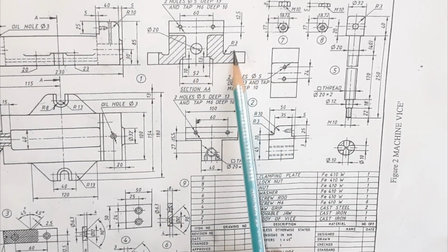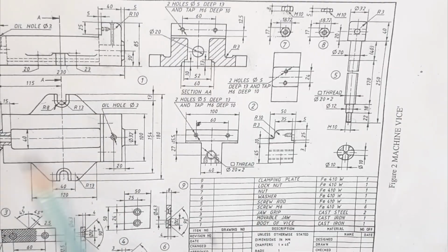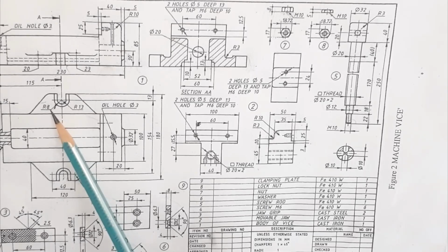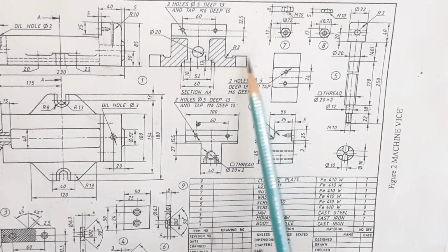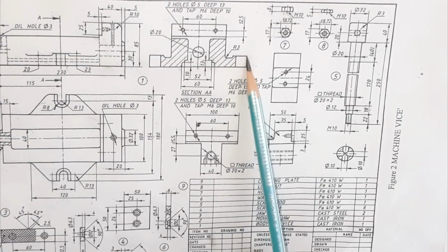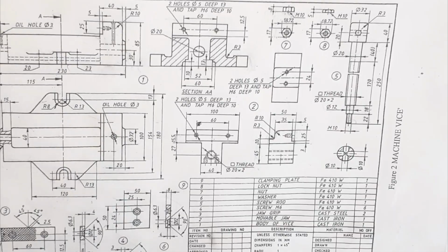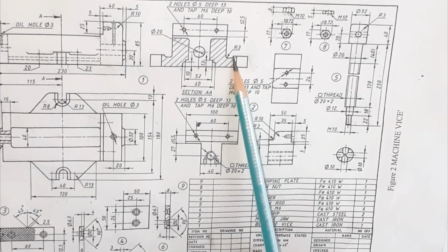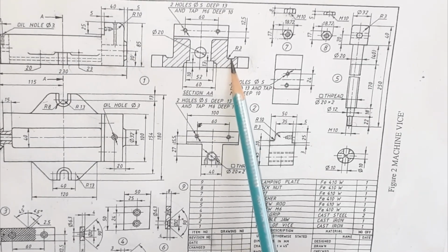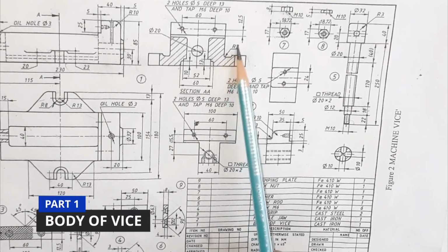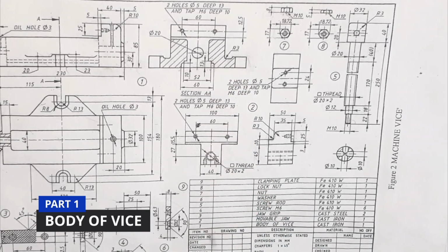Next, let's draw these two boxes here. So what will be the distance of this box? This box is nothing but 13 mm plus this 8 mm. So 13 plus 8 is 21. So this length is 21, and from here to this end, that is 13 plus 13, that is 26 mm. So from here to the edge of this is 26 mm, and then from here to here there is a line which has a height of 20 mm, and at the end there is a radius of 3. So let's first draw this part.